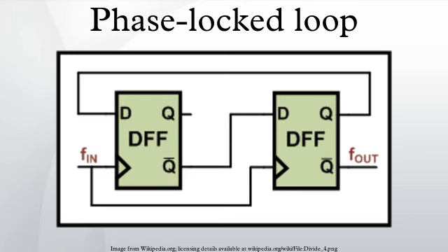Digital phase-locked loops can be implemented in hardware, using integrated circuits such as a CMOS 4046. However, with microcontrollers becoming faster, it may make sense to implement a phase-locked loop in software for applications that do not require locking onto signals in the megahertz range or faster, such as precisely controlling motor speeds. Software implementation has several advantages, including easy customization of the feedback loop, including changing the multiplication or division ratio between the signal being tracked and the output oscillator. Furthermore, a software implementation is useful to understand and experiment with.